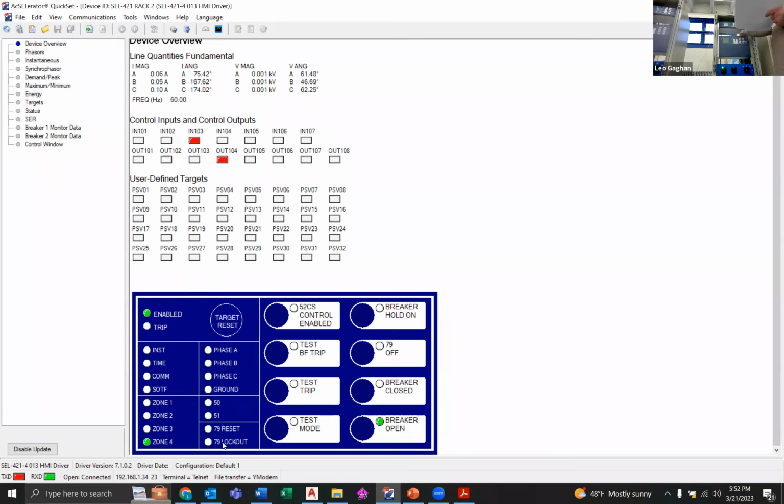And then I talked about the switch on default. We can walk our way through how that might work. So let's say the breaker has been open for a long period of time. Someone's going to come through, and rather than it being a reclose, they're just going to do their manual close. So they come through, they do a manual close. Oh, we immediately trip out. Okay, no reclose.